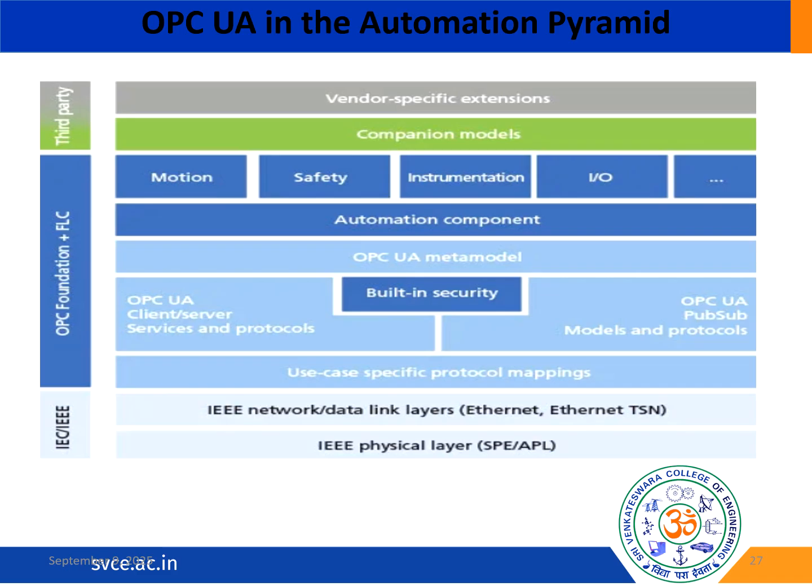Industries nowadays are used to vertical integration using OPC UA. Each component in the industrial process, such as controller, sensor, robot, camera, and measuring device, serves as an independent machine unit, which itself serves as OPC UA server and OPC UA client at the same time.